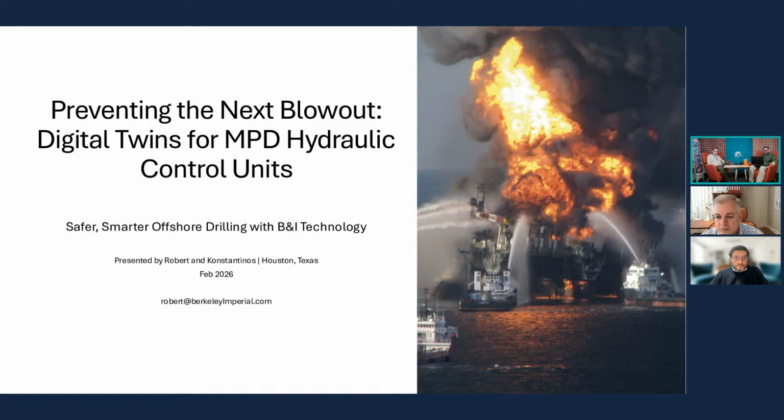But for those interested, what you can do is go into the System Modeler webpage, click libraries, and you will find the OPC-UA library. Then you can see screenshots of how it's connected, and it's basically the same drag and drop as you would do with any other Modelica library. It's just that you configure communication with other systems with it. Yes, and I've shared a link to the library store in the chat.